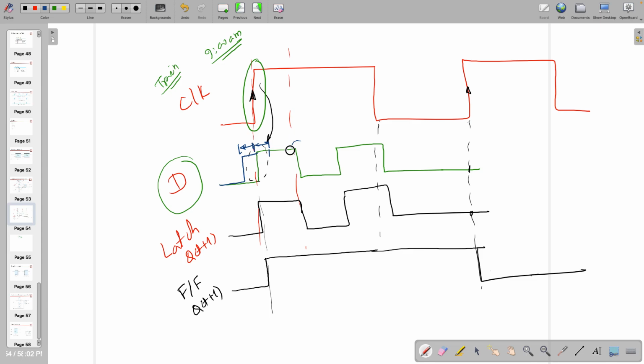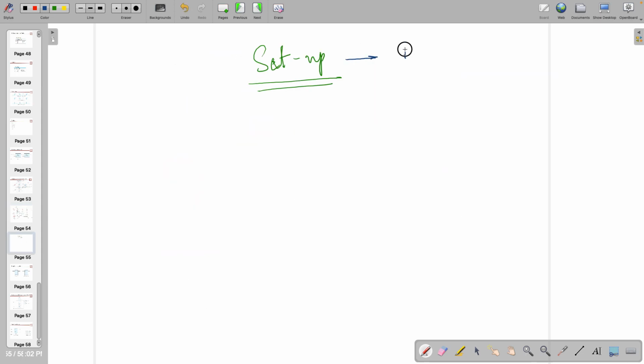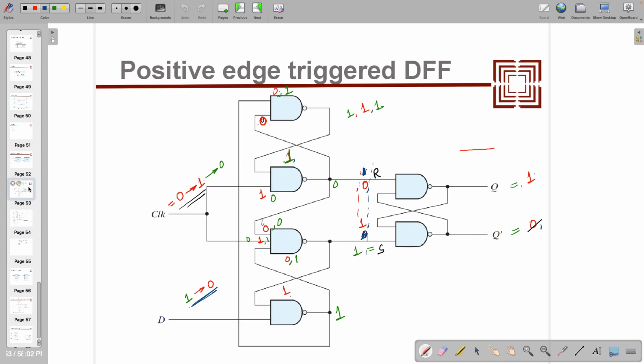So the same thing is happening here. Even though somebody has gotten down, he wants to go to Delhi, but he gets down at Jaipur, still as per our record, it's like he is going to Delhi only, right? So this particular situation, being there before the time, is known as the setup time, and sitting inside the train is actually the hold time, the time after. So some small window will be given, depending on how you are designing the gates, depending on the setup time and hold time, and you should not violate that. If you are violating, it means your answer will be different than what you are expecting, right?